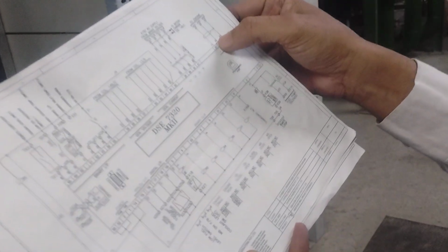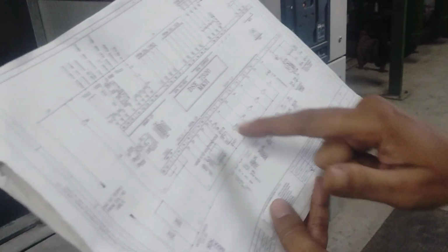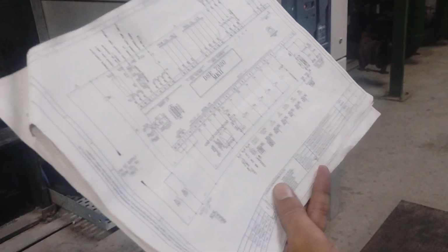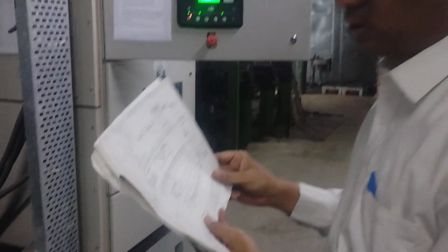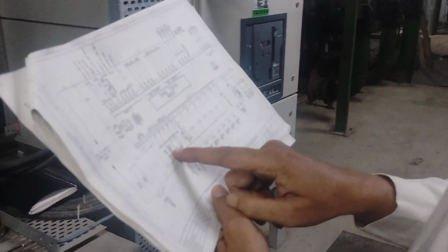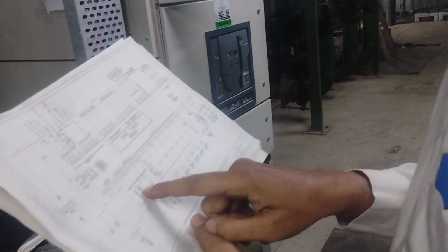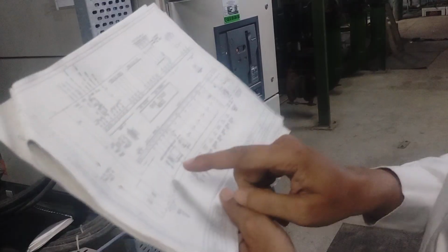And these are the various inputs which are connected and configured to the DSE electronics. This is the MPU sensor for the speed controller. These are the remote start, stop, breaker control, breaker on, off, and engine crank, engine run. These are the analog inputs for the oil pressure sensor and coolant temperature sensor. The oil pressure sensor is a VDO 10 bar. This is a diaphragm based transducer and sensor, and this is the coolant temperature sensor PT100. This is also a resistance based analog input for the temperature controller, and the VDO 10 bar is the oil pressure sensor.